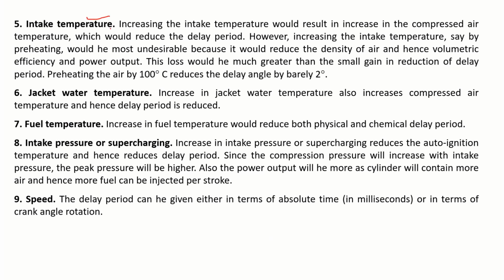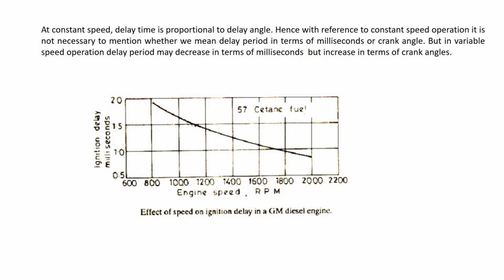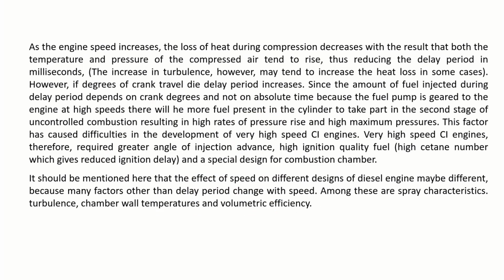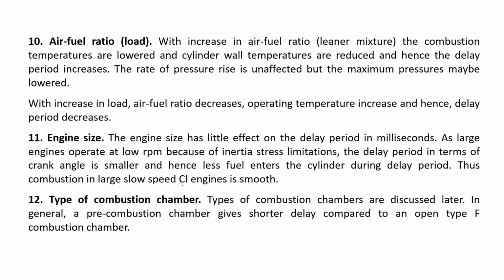Increasing the intake temperature will definitely improve it, but it will affect the volumetric efficiency. Jacket water temperature will improve the ignition delay, meaning it will decrease the ignition delay. Fuel temperature, intake pressure and supercharging: yes, all this will definitely improve this. Okay, so we can optimize the parameters so that the ignition delay is minimum.